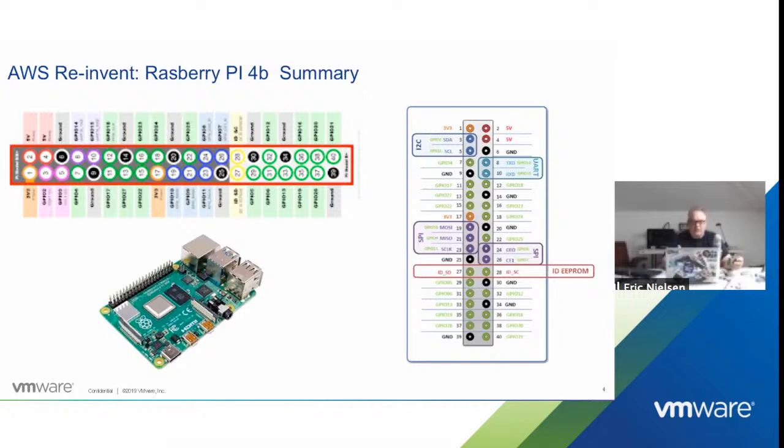So you can split the power pins out if you need to. It's just a power rail, and you can hook many devices up onto that pin if you want to. Same with the 3.3 volts. Plenty of amperage there. So with the Raspberry Pi, you can run probably 100 sensors without running out of power, because these sensors don't use a lot of power.